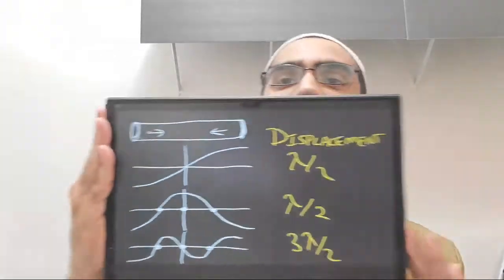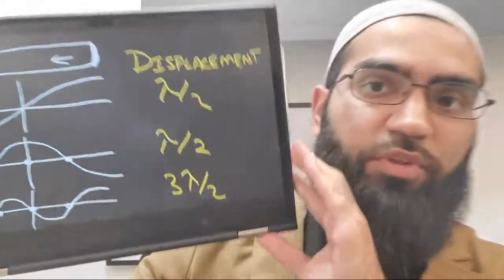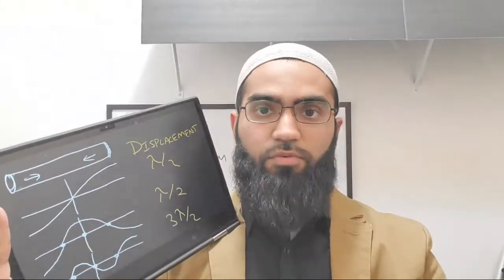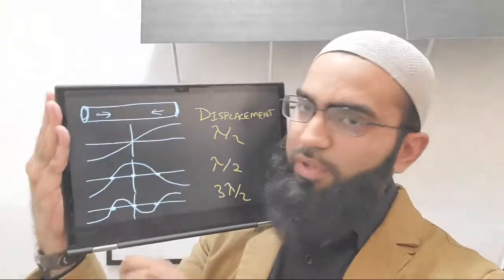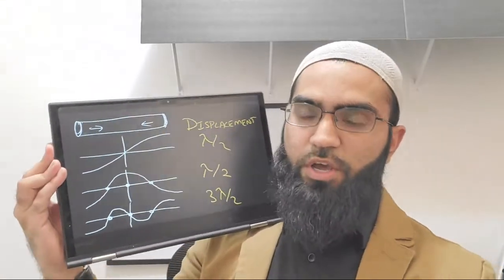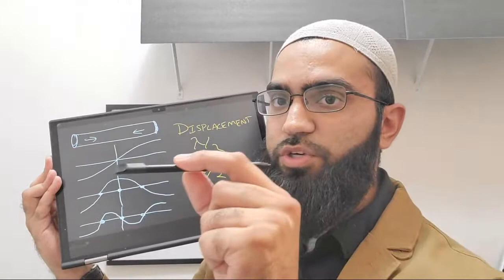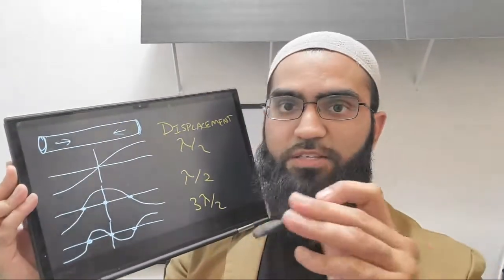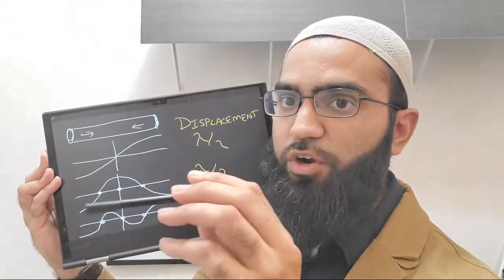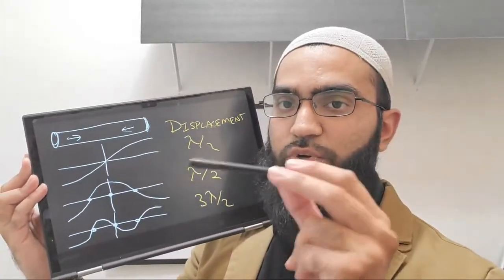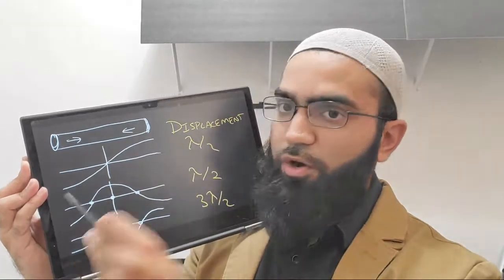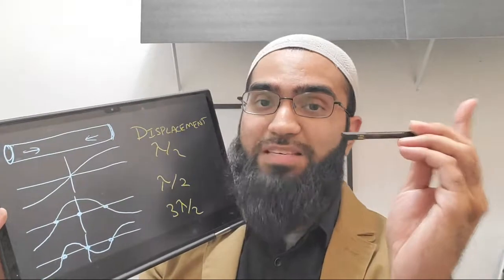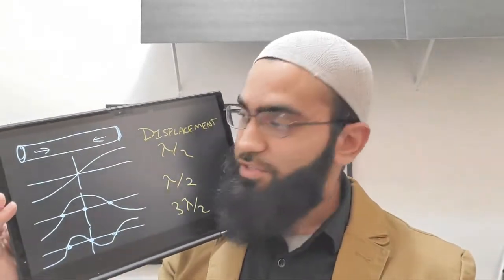So here's where we get to the actual practical significance of wavelength. We have a rod here, and if you just have it free floating, it's going to have free boundary conditions, and those free boundary conditions are zero strain conditions on the bar. What this basically says is that any excitation that occurs, the resonant frequencies that it's going to stimulate are going to have basically zero stress, which is also maximum displacement conditions on the edges.